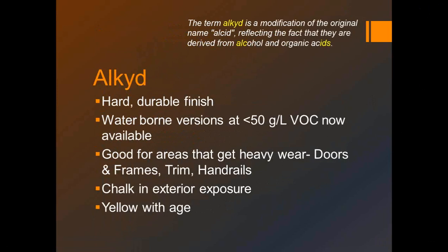But if you take a look at the side of the bucket, there are prime coats normally recommended for other substrates on that primer and paint primer in one type finish coat. So make sure that you're doing your due diligence and reading the label before you actually grab a bucket and head for your job site, because there are some mitigating circumstances in some of those products. Okay, great, thanks.